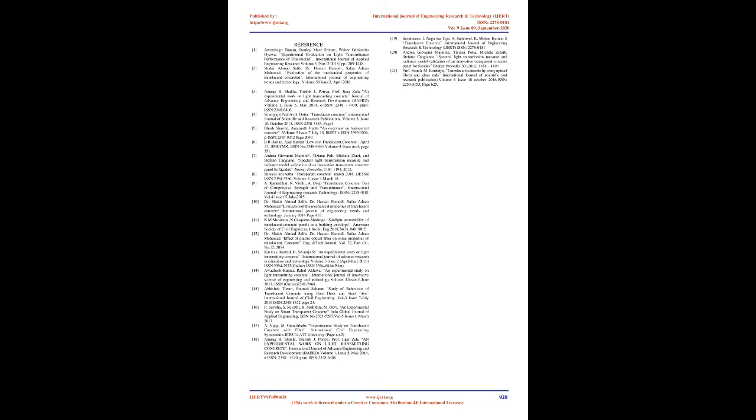They were tested for compressive strength and light transmittance property after the required curing period. The light transmittance test was performed to study the light transmittance characteristics of the specimens. It is a very important test since the main purpose of translucent concrete is to transmit light. Drying of cubes after casting. Curing of cubes. Cubes after curing for 28 days. Sunlight passing through cubes. Light transmittance property test: 100 W, 1500 lumens, incandescent source of light.